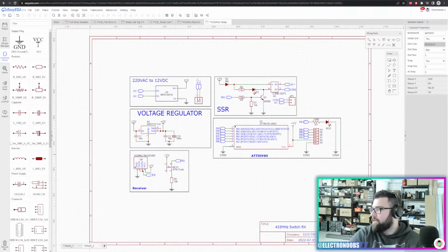If saving space is needed, stick to 0603 resistors. If there are multiple resistors nearby, use a network resistor. Yes, you can also find a network resistor, which basically is a few resistors merged together in the same component. You can also use that, but I think those resistors are always the same value. I'm not sure, but I think they are always the same value.